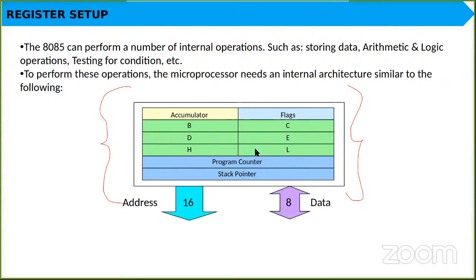To understand your entire operations, if I do 1 plus 2 or 2 plus 3, all these things get stored inside these registers and then it moves to the ALU. So basic things you have to understand. The data is stored in the memory, comes back to my CPU via these registers, goes into the ALU, I get a result, and the result is stored back into the memory. This sequence is what is important for you to understand, at least for this 8085 part of it.